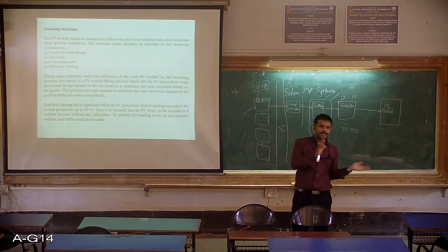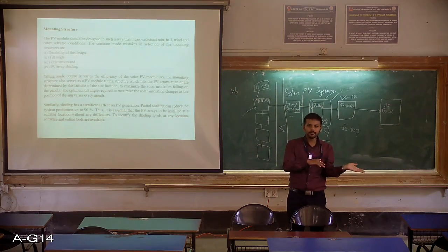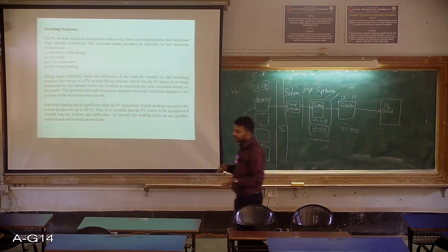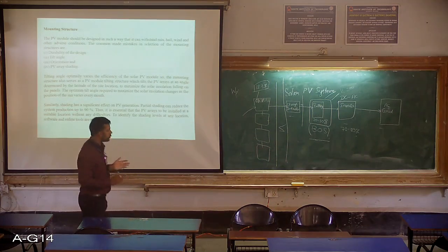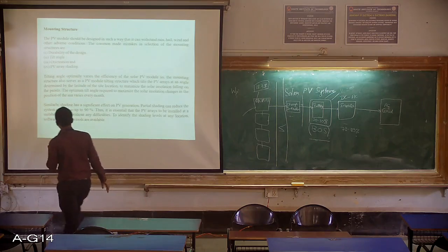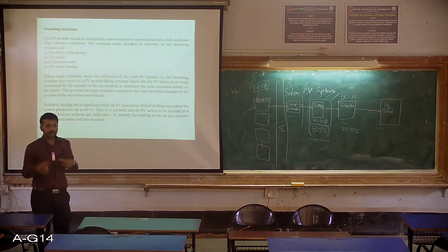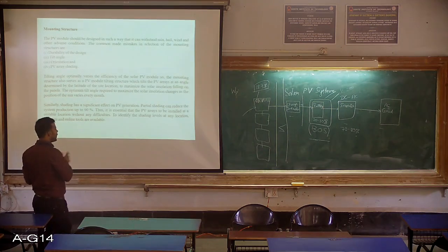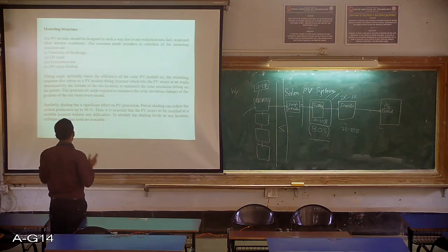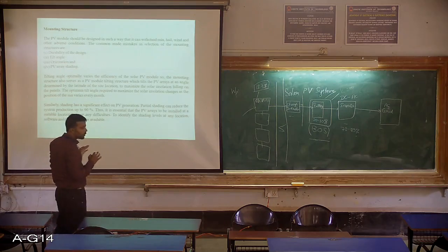So one is daily, the sun moves from east to west, and the other is that throughout the year the path of the sun changes. So this tilt angle is a very important, crucial point to extract more power or to increase performance. Whenever we consider the mounting structure, we should consider the tilt angle as a very important point.